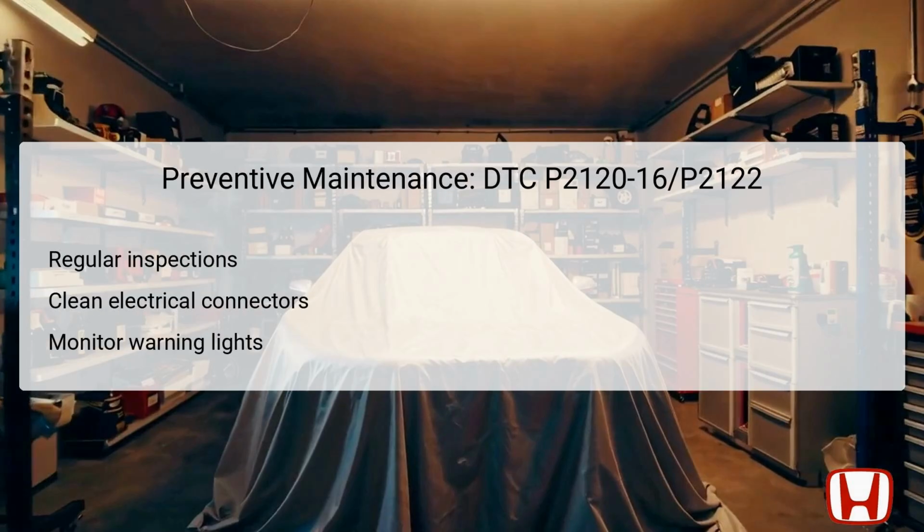Preventive maintenance is vital in ensuring that issues like DTC P2120-16, P2122 do not recur. Regular inspections of the accelerator pedal position, APP sensor, and associated electrical connections are essential to detect potential problems preemptively. It is recommended to clean any electrical connectors regularly to remove dirt and corrosion that might impede proper signal transmission.